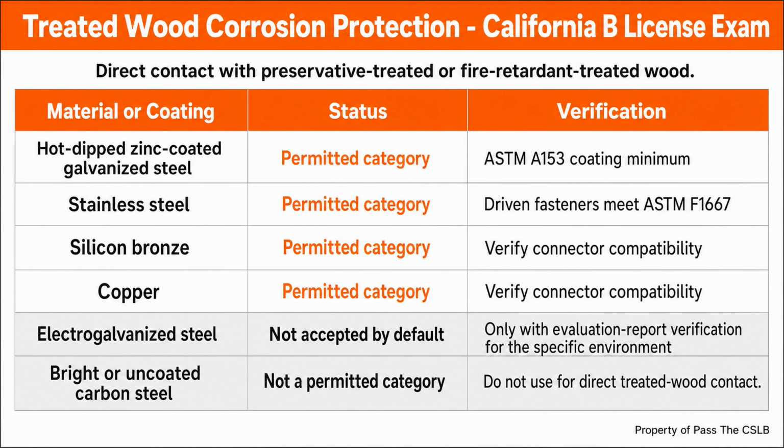I use a 3-pass inspection for connector work. The first pass happens before installation. I verify the connector model, the plans or approved detail, the manufacturer instructions, the evaluation report when applicable, the fastener package, and the exposure condition.